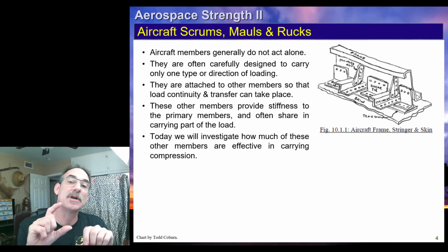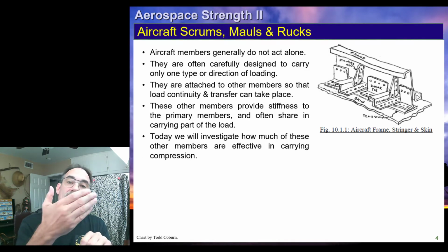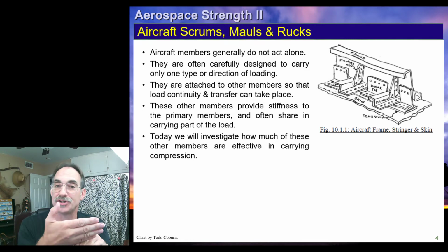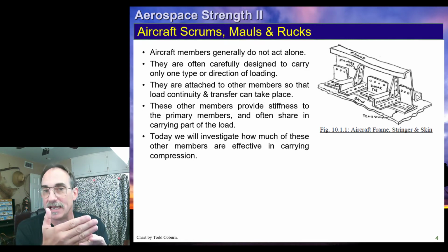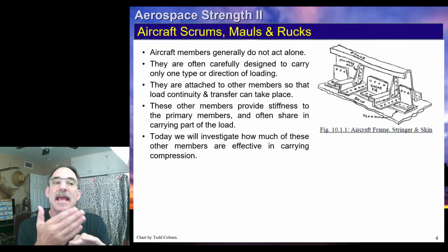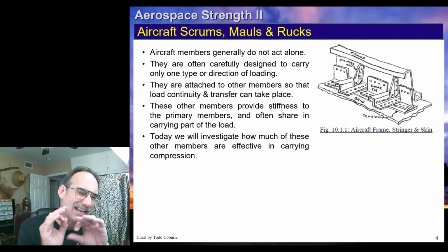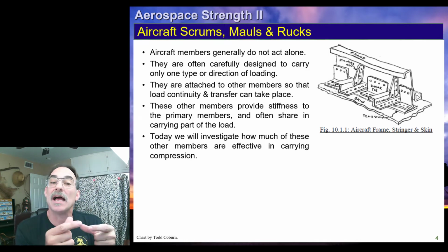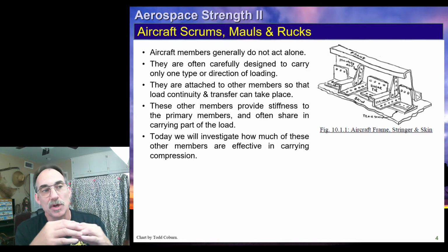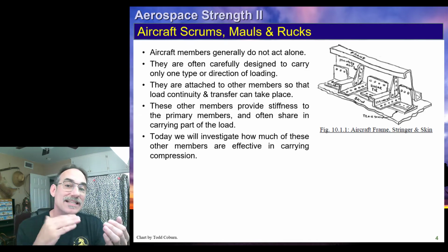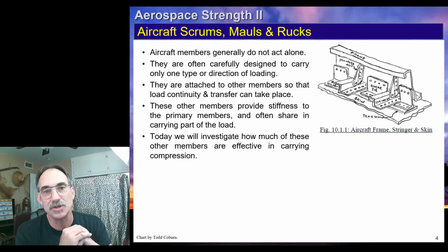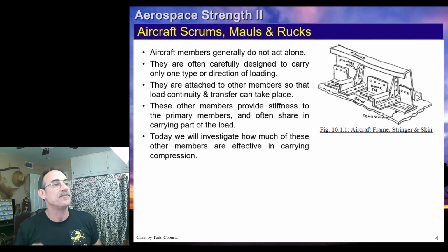We'll have little stringer clips which tie the frame to the stringers so the stringers get supported at each frame out of plane and to tie the frame down even slightly more. And then we'll have little tear strips which are in there to help arrest cracks that may run longitudinally or in the circumferential direction on your fuselage structure.